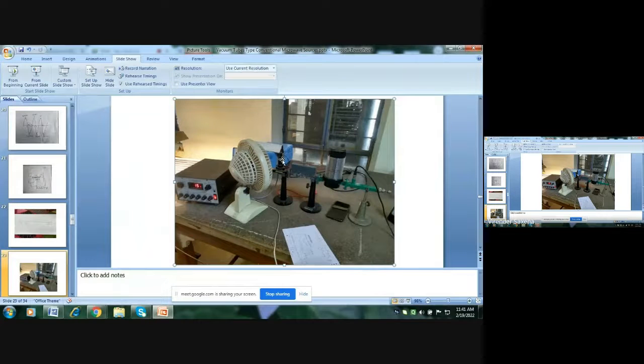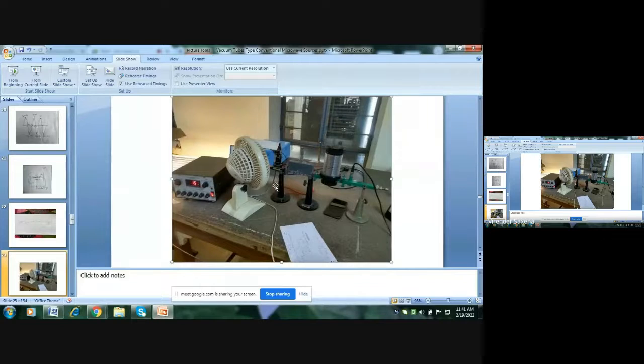So there is a device called Klystron mount, and this Klystron mount is having a plunger like this, and this plunger is used to match the impedance of this Klystron with the waveguide.